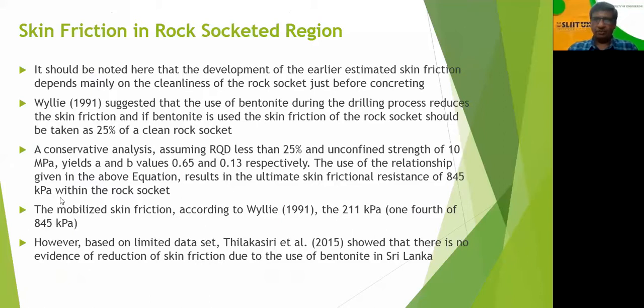So if you use a normal case, a normal situation, like if you assume RQD is 50, then the strength, the uniaxial compressive strength, is about 10 megapascal.